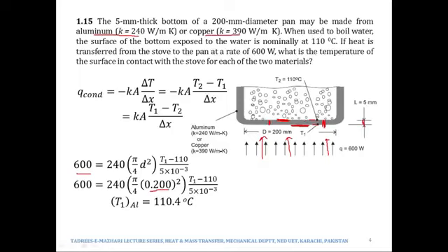Similarly, the lesser the conductivity of the material, means if the value of K is small, the same phenomenon will happen, it will offer more resistance, because if it is not highly conductive, then it is more resistive in nature. So it will not let the heat flow that easily. So it will also result in more temperature difference between the two faces.